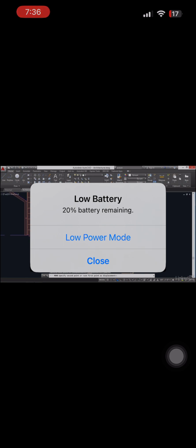So I've picked up the chair from a very precise point on it. Now I'm going to snap that chair to the midpoint of this slab line. So again, I need to hold down Shift and right-click to access this menu. I'll choose Midpoint and then click right here, and that completes the Move command. So I've done this because I now have an intersection point, the intersection of this line and the backrest of the chair, that will act as the base point of a rotation.